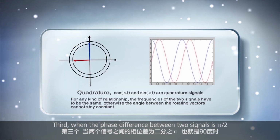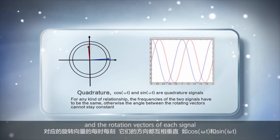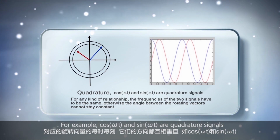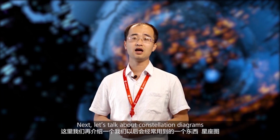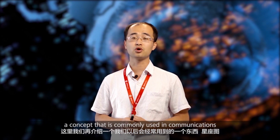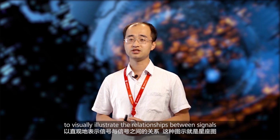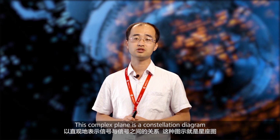Third, when the phase difference between two signals is pi over 2, we say that they are quadrature signals, and the rotation vectors of each signal are perpendicular to each other. For example, cosine omega t and sine omega t are quadrature signals. Next, let's talk about constellation diagrams, a concept that is commonly used in communications. In digital communications, digital signals are often represented on the complex plane to visually illustrate the relationships between signals. This complex plane is a constellation diagram.